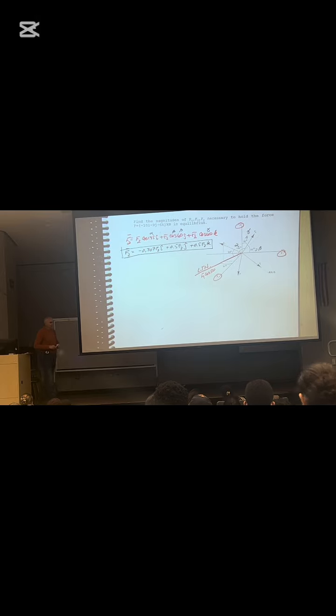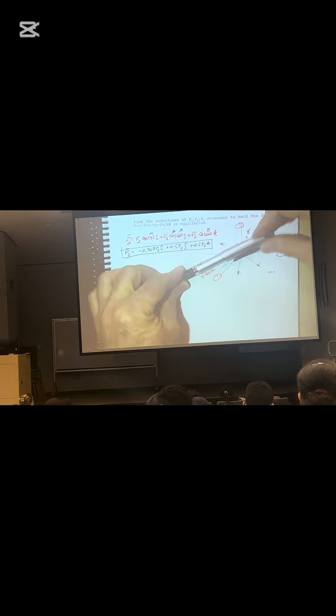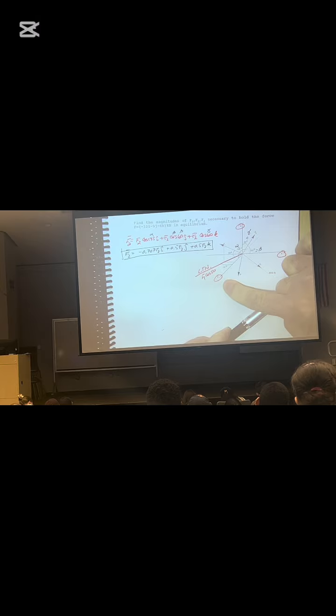All right, so the line to nowhere, we call it the line to nowhere because it's not an x, not a y, not a z. It's not parallel to the x, y, or z. It's sticking out in space someplace. So if I want to project this force to the x, what do I do? I take this and swing it cosine 30. Where do I land after I swing cosine 30? Along the x.